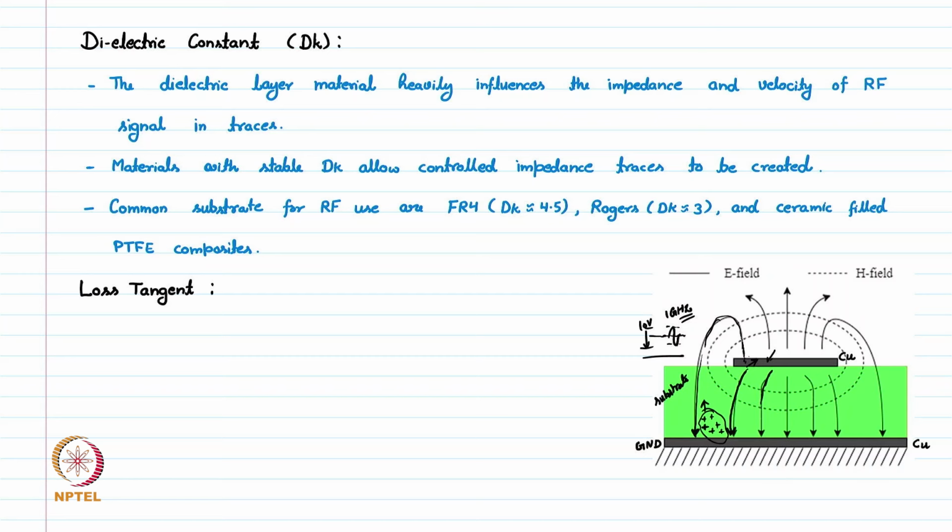It means our signal will have certain loss in propagation due to the frequency of that signal and of course the voltage. So, our signal is degrading or having loss while traveling from point A to point B, and that is because some of the loss is happening inside the substrate itself because of this charge induction.